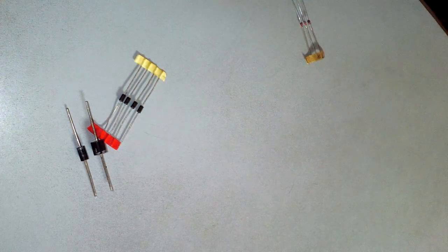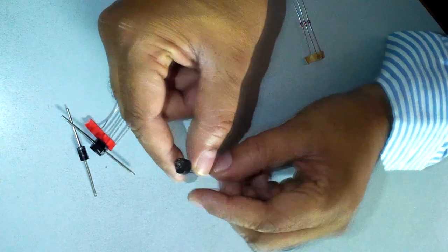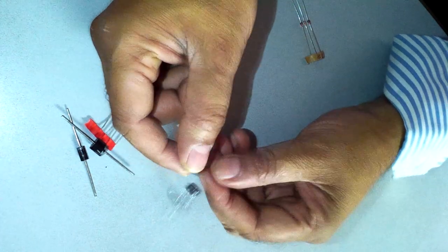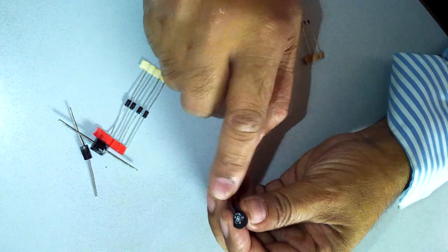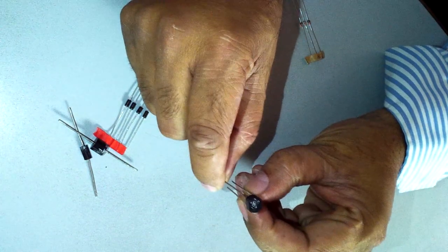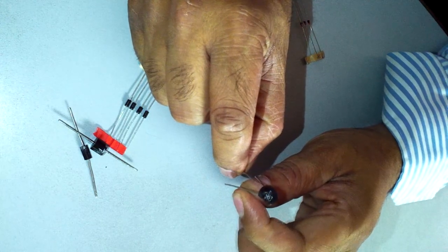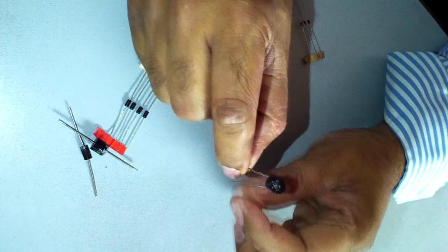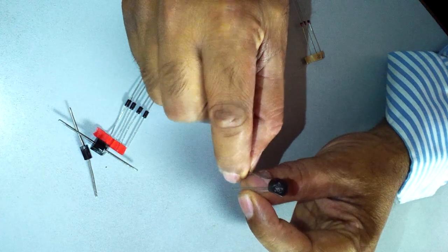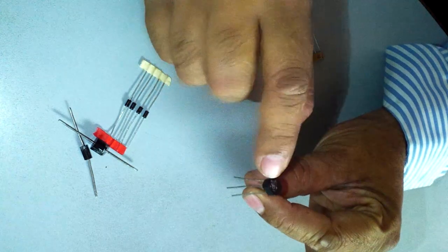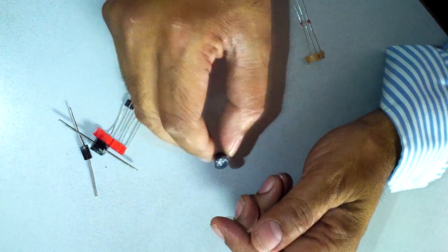An interesting thing here, I would like to show you this. This is a full bridge rectifier completely. It has 4 diodes within it. 2 of the leads are connected to the AC, and 2 of the leads are connected to the unidirectional port, that is plus and minus. To those unidirectional port pins, you connect the load resistor or even the filter capacitor. So this comprises 4 diodes within it. It's a full bridge rectifier component available to you.